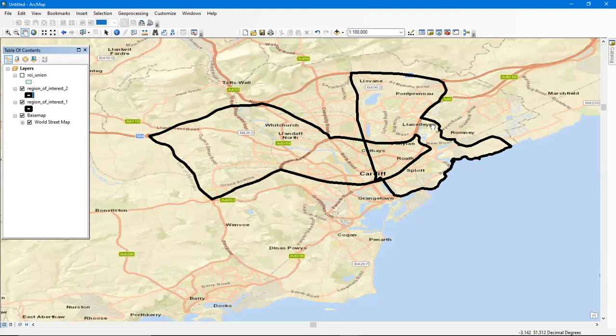So once the data is georeferenced, then you can add a base map so that you can visualize this data in a base map so that it can fit in your base map exactly where you placed it from where you are collecting. If you are collecting data from a field and then you load a base map, when you zoom to the layer, it should go to that point where you are collecting the data from. So that is how we add base map.